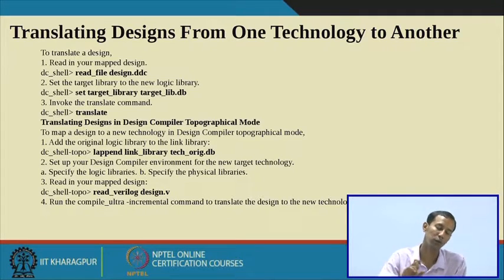That means once you have loaded that corresponding new library into the Design Compiler environment, then you put your translate. So the whole design will now be mapped to the new technology library file, okay.